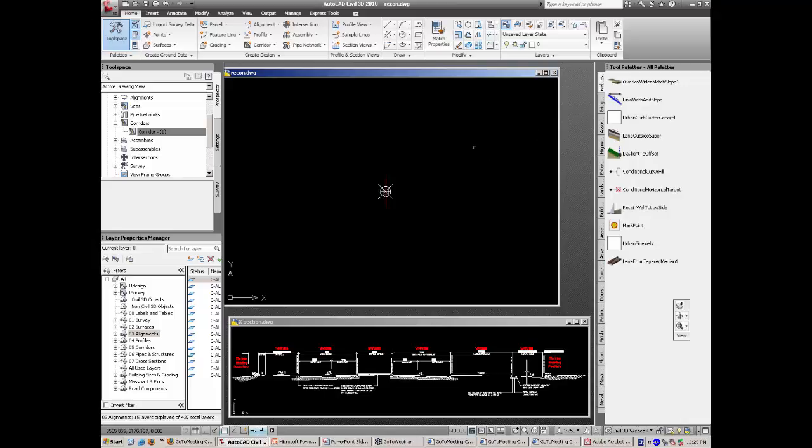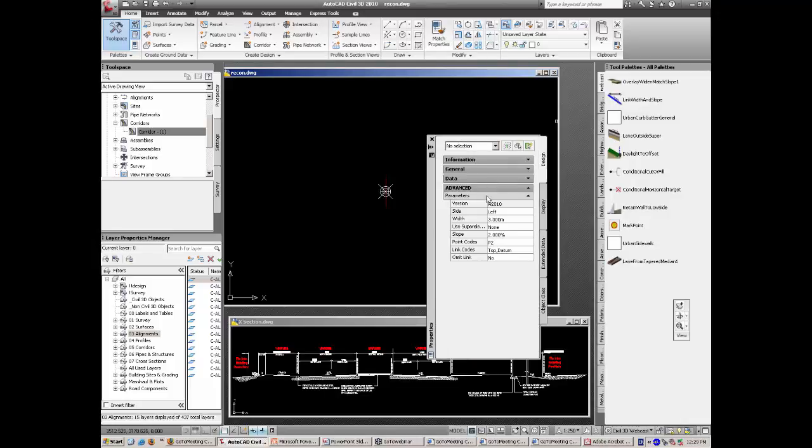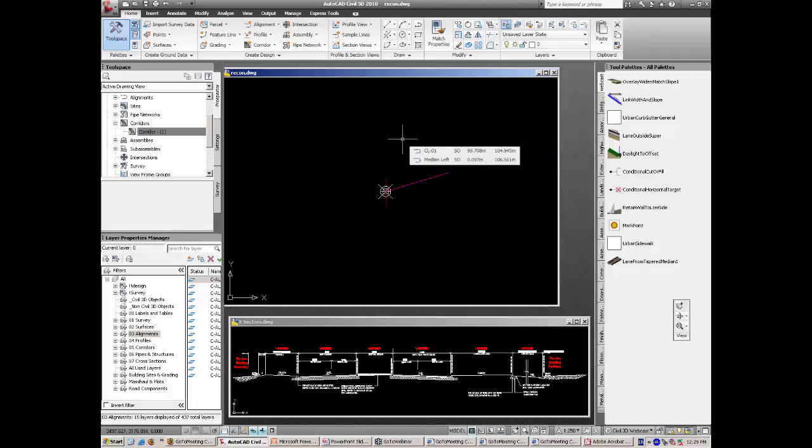So the first one I want is link, width, and slope. So I press that, and I want to link to the right-hand side. So I'll select to the right. The width I want to go to is going to be, we'll say, 6 meters. This is arbitrary because we're going to change it with the alignment strings anyway. And the slope, I'll give, say, 30% to make sure it stays off my main cross-section so I don't get confused. Now that's enough to begin with. I attach that here, and what we will see is a simple line coming off our center line to allow us to offset to the right-hand side. So that's good. That's our starting point.